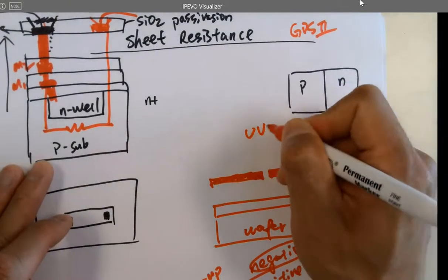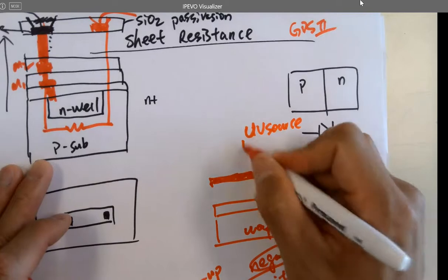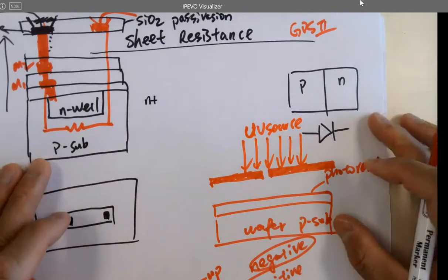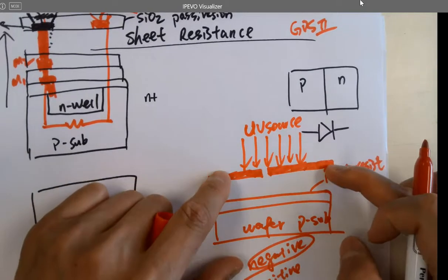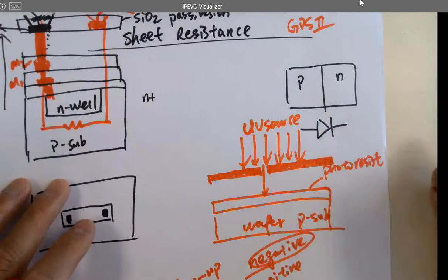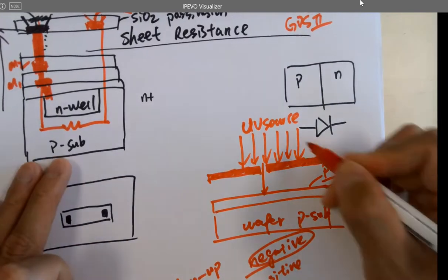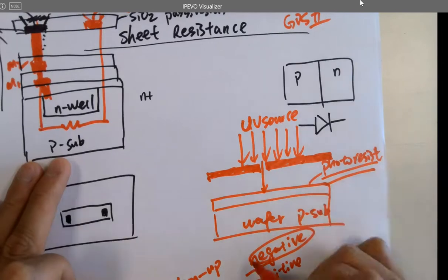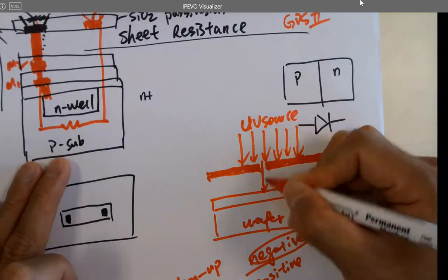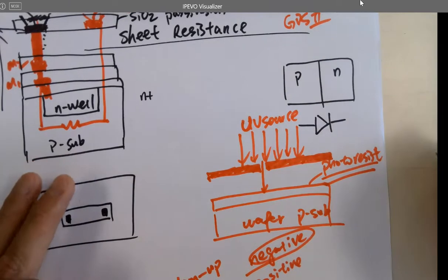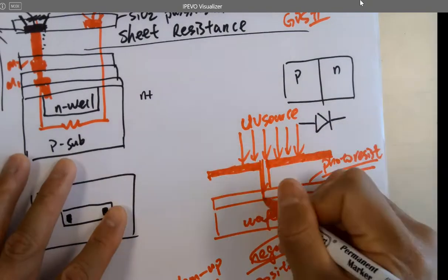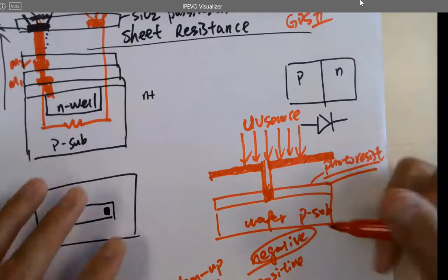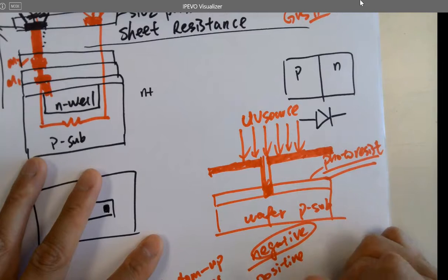And you have a UV source here. Shine UV. What's going to happen? The ink here will block the UV, but here the UV will reach the photoresist, which is a material sensitive to UV. So as a negative photoresist, whatever is exposed will stay on the wafer afterwards, after you put the whole wafer into a chemical called developer. So only here is exposed, and the property of the material will be changed because it is sensitive to the UV light. It's a cross-link.